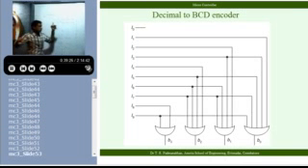Or you have got a pressure signal, you have got an equivalent voltage, you have taken a sample, and you want to display it in terms of a particular scale factor, either PSI or bar, millibar, kilograms per centimeter squared, whatever. Depending on the conversion factor, you have to put a corresponding BCD multiplier and work with that. I'm just giving a typical example.